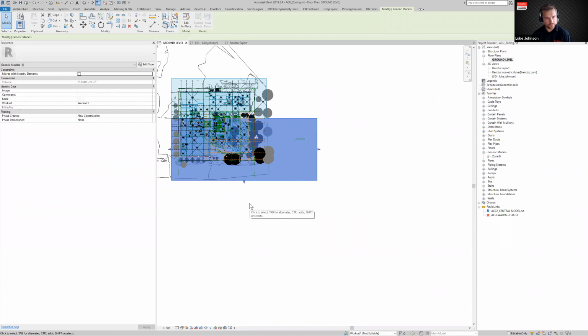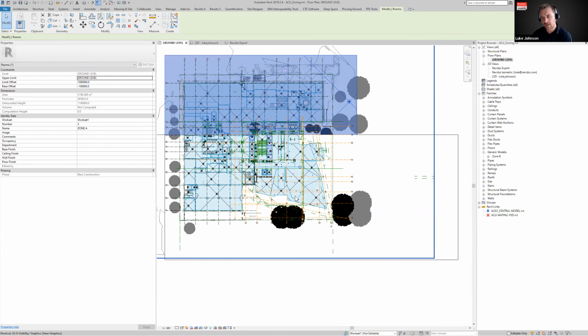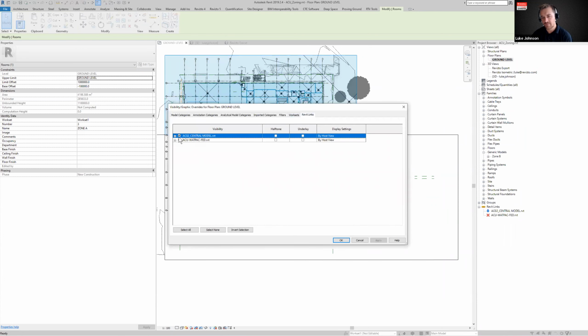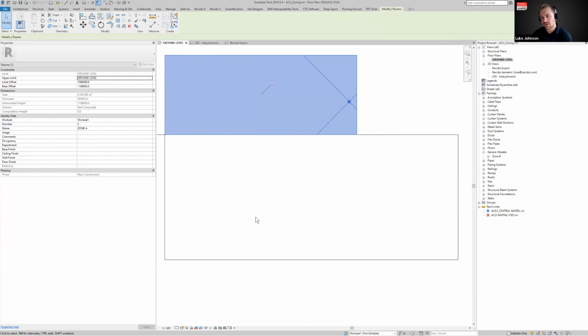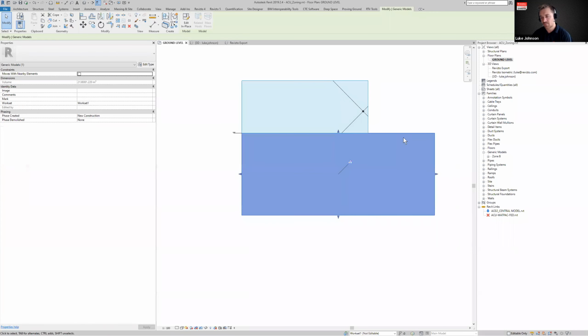Now, as you know, Revit likes to only have one set of rooms in each model. So in this particular case, what we would want to do is create a separate model called zoning, and we could place a room in it. You're seeing the architectural link in the background. If we were to hide that off, we can then see that we've got this object here, and it's named like so. So these are two different ways that we can use massing objects or room objects.